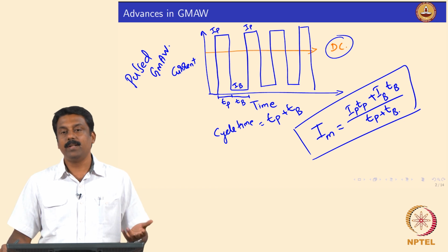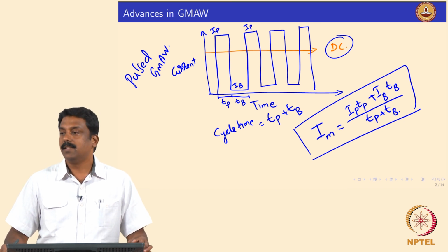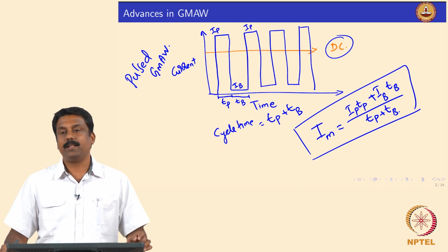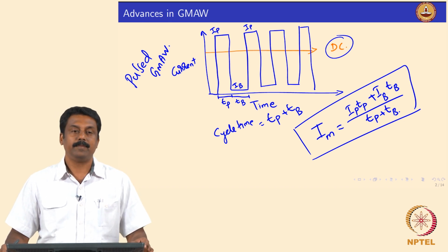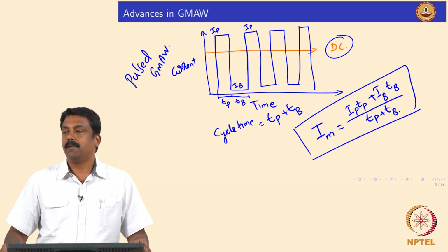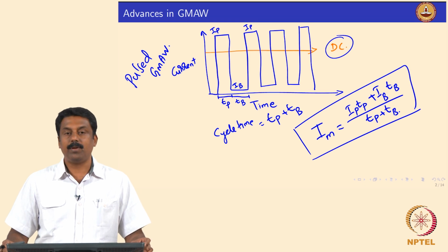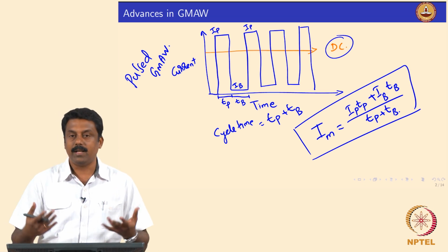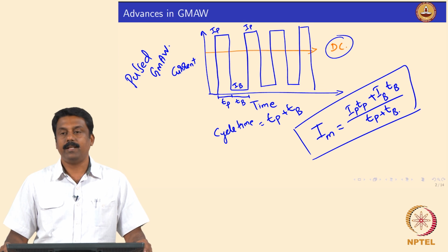Okay. So, your heat input or arc energy decreases significantly without compromising your productivity and the process stability. Such waveforms are very widely used to achieve spray transfer in the GMAW process, and by doing so you also reduce the amount of heat you put in the material while welding.